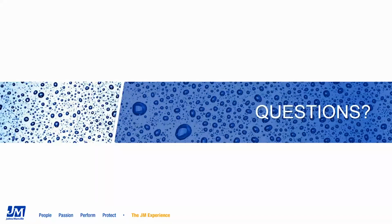All right, thank you. Marybeth, the next question is for you: why do cyclical conditions increase the potential or probability of corrosion? Even if your normal temperature operating range is outside of what would be considered the severe CUI range, bringing your process up and down will likely take you through that temperature range that is specifically bad for CUI.